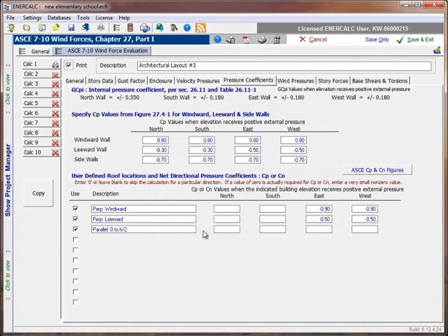and say that we're going to set up an item that is for wind parallel. So we know when we're talking about wind that's parallel, we're going to be working in the north and south cells of this CP table. And to begin with, it'll be a minus 0.9, minus 0.9, north and south. Notice that I'm leaving the cells blank where I don't want a value calculated.